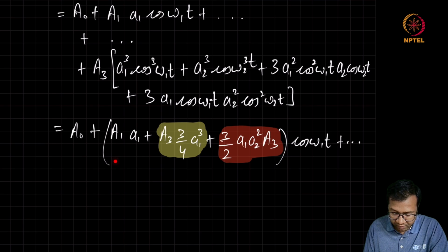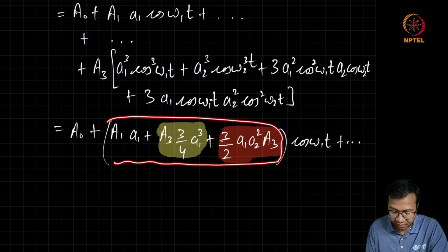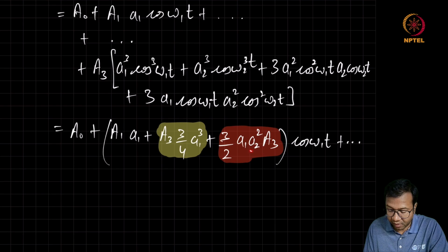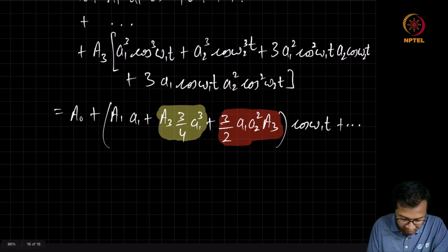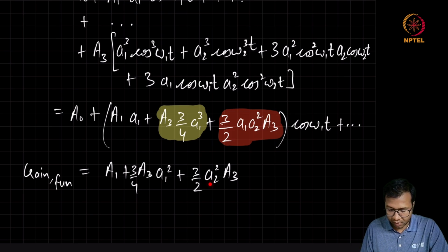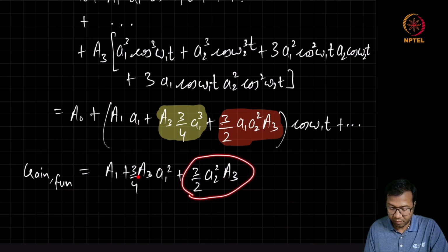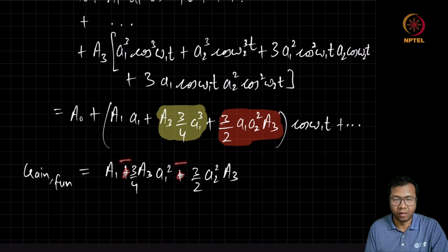And overall, it can cause huge desensitization of the gain. So now if A2 is pretty high, then compared to the gain at small A1, meaning without interferer, we are going to get an effective gain which is different. If A2 is pretty high and the system is nonlinear, then this term can dominate the gain, and in most cases A1 and A3 are going to be of opposite polarity. So there will be a huge reduction in the gain for the desired signal.